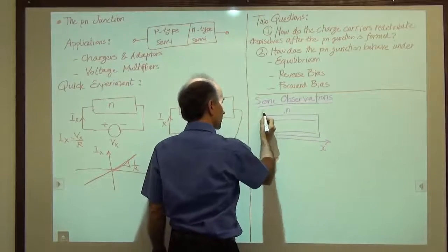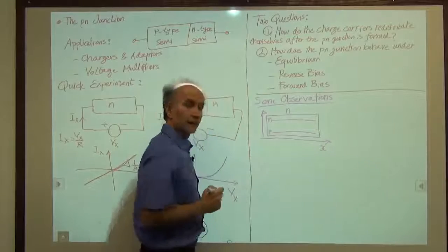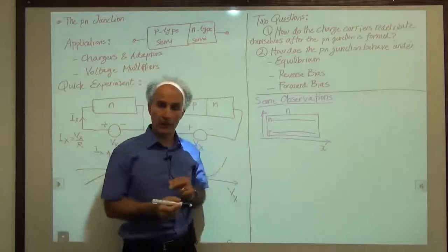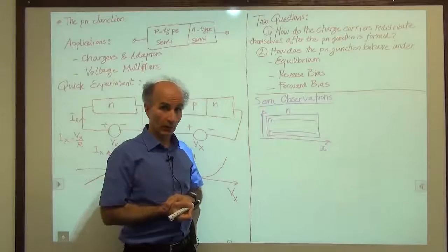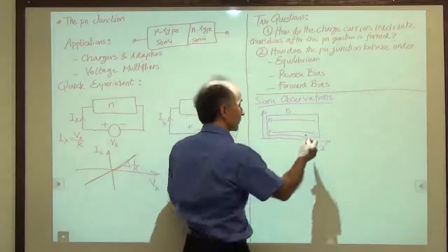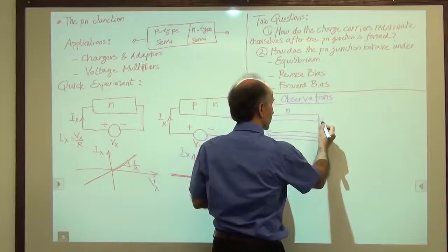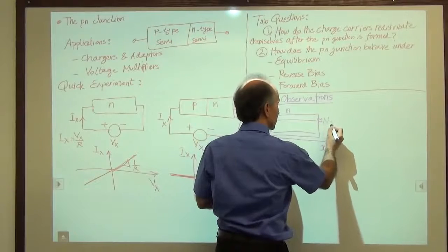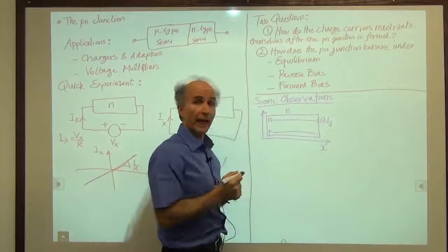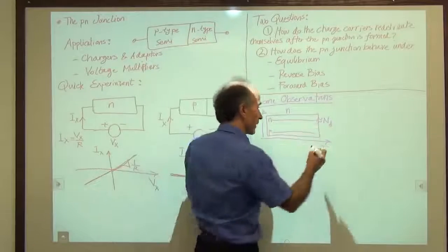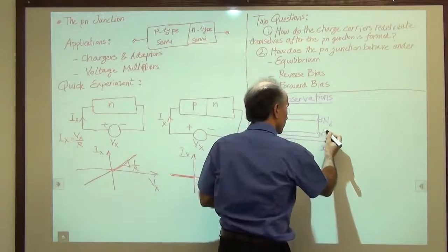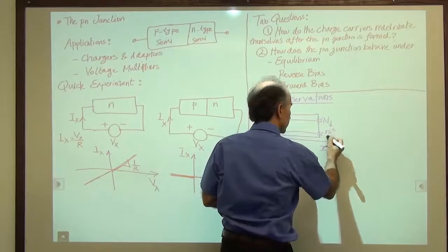And that is the concentration axis. N is very high, p is very low. How much is n? Remember the equation we had. N was actually about equal to Nd, the number of donor atoms per cubic centimeter, and p was ni squared divided by Nd.